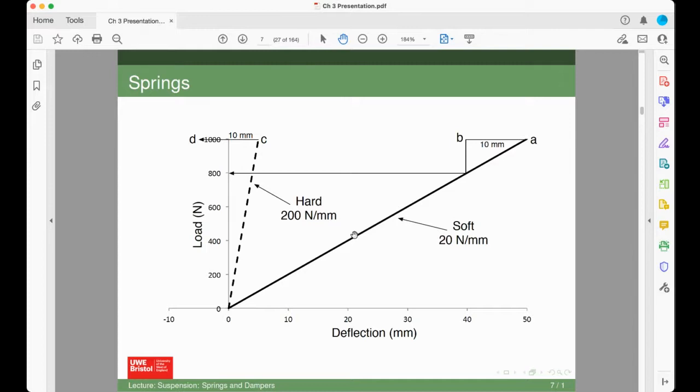And another anecdote about that: back when the R35 GTR came out, the Nissan GTR, a number of years ago now, one of the things about it was the double clutch gearbox and launch control. This mighty vehicle could launch extremely far and extremely well. But to get it into launch control, there were various settings: you had to put the gearbox and the throttle in R mode, and there was also an R mode for the suspension. To actually get it into launch control, you had to make the suspension soft, and the whole idea behind that was to get better traction.